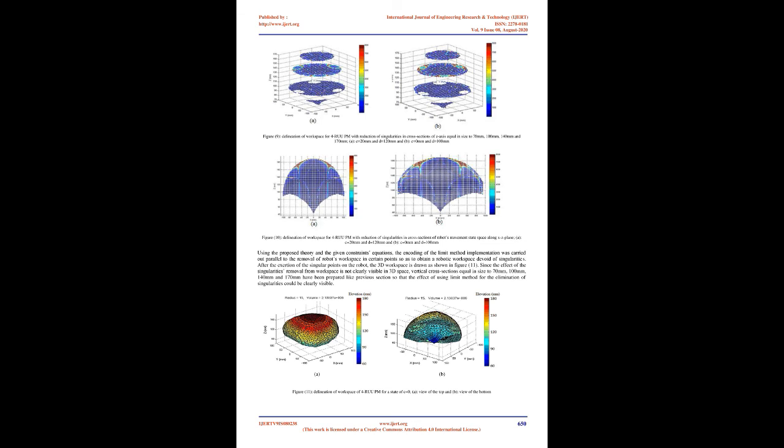In the delineated diagram, the light blue and red points are adjacent to the singularities, hence having a worse situation than the other points. Comparison of figures 9a and 9b makes it clear that, upon getting closer to 0, the length of the link C provides for a higher likelihood of singularity occurrence but for a lower number of points. It means that the link C covers the singularities, hence it is useful for the expansion of the workspace.